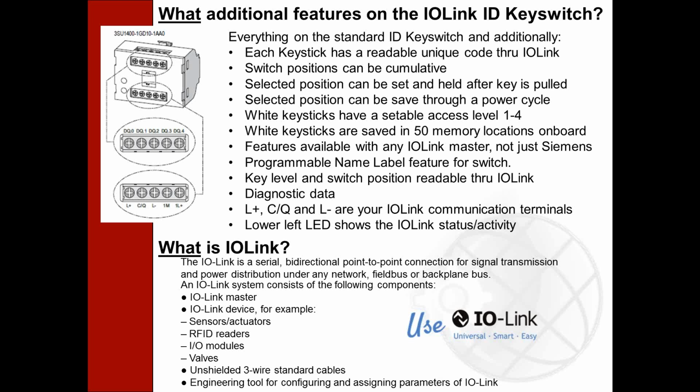If you Googled IO Link, you would learn a lot more about this, but at this point we're not going to go into very much of a deeper dive into IO Link, because that opens up a whole bunch of information that we're just not going to have time to cover here right now. But IO Link uses the unshielded 3-wire standard cables, like we're showing, the L+, the C/Q, and the L-. And typically there's an engineering tool for configuring and assigning parameters of the IO Link.